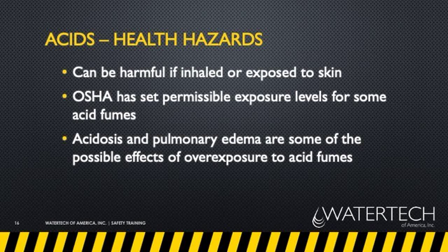Read labels and SDSs before handling any chemical. All of you have personal protective equipment to wear. If you are getting product on you, it's probably more negligent on your part, not wearing the right stuff at the right time. If for any reason you feel you need additional safety equipment, anything, just bring it to our attention. In addition to physical contact with acids, you also need to worry about fumes.